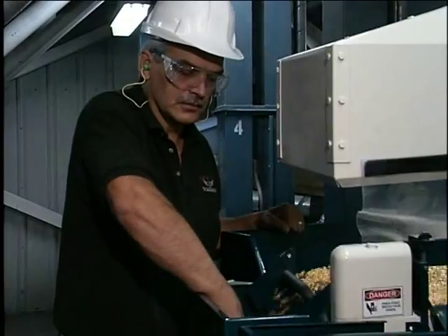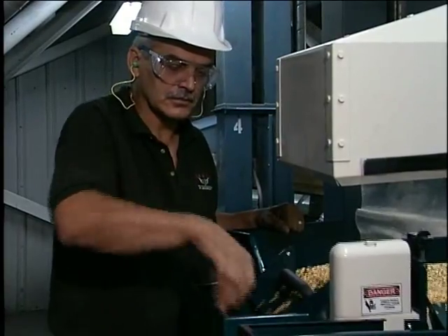If too much of the flow is returned to the deck via the rerun conveyor, then you will observe a buildup of light product on the deck during the course of a run. Correct this problem by moving the splitter towards the heavy product discharge side. Less material will go to the rerun conveyor and more will go to discard. A skilled operator can use this splitter to achieve a balance between maintaining product quality while minimizing discard.